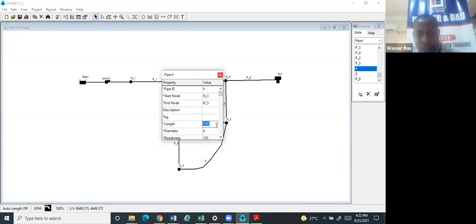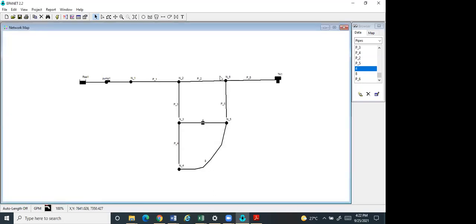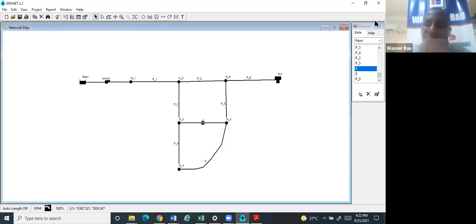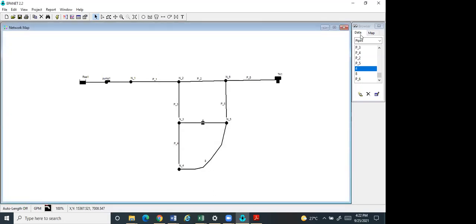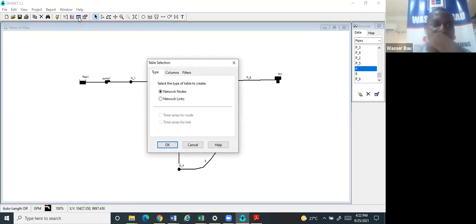8 and excuse me, is there a view where I can see all pipes and all nodes I drew? So basically on a quick look I can see if I maybe missed something to add. Okay, go to table. Go to table here. Click on table. When you click on table, you say link.